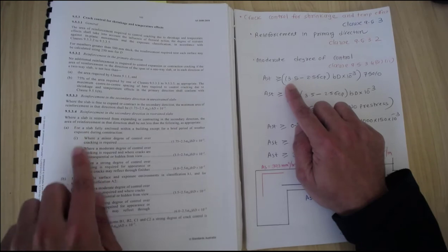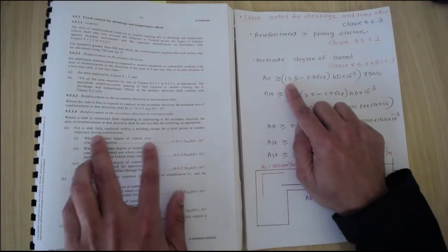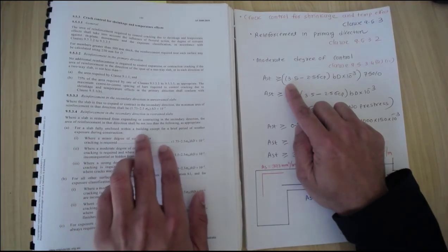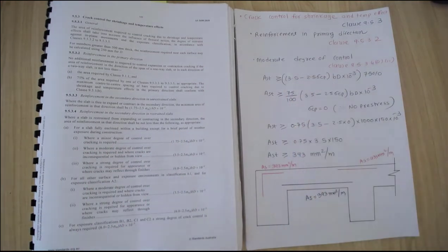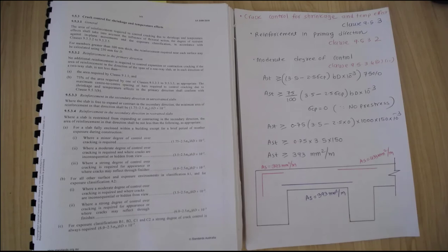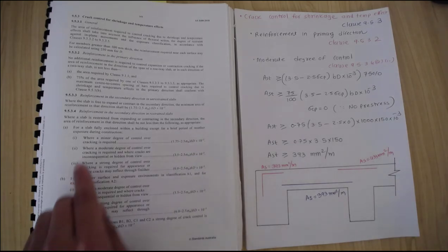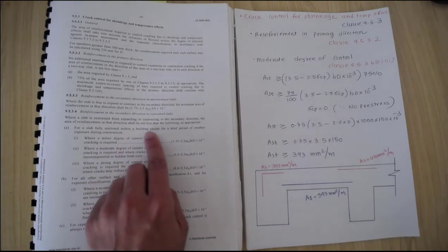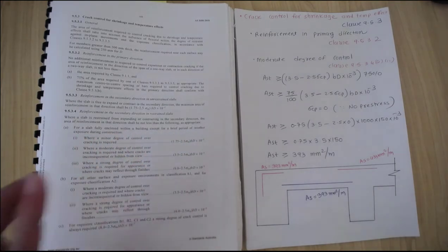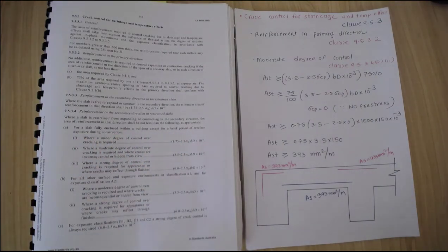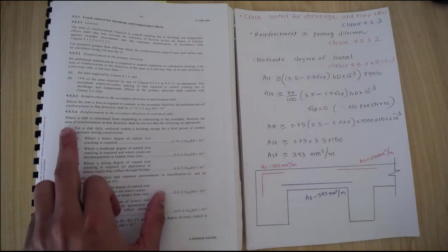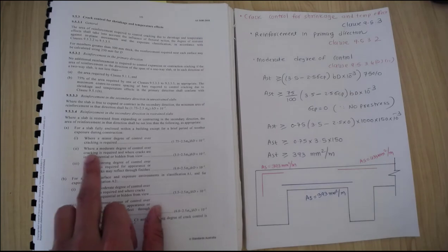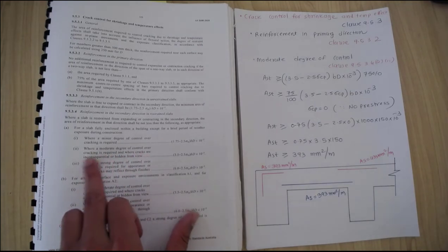There are different exposure classifications: fully enclosed within the building, brief exposure varied during the construction. It does not say anything in our example, but we can make an assumption that the slab is fully enclosed within the building for a brief period, so let's say the slab is located inside the construction. In that case we are taking this A, and in that one let's do the moderate degree of control over the cracking.